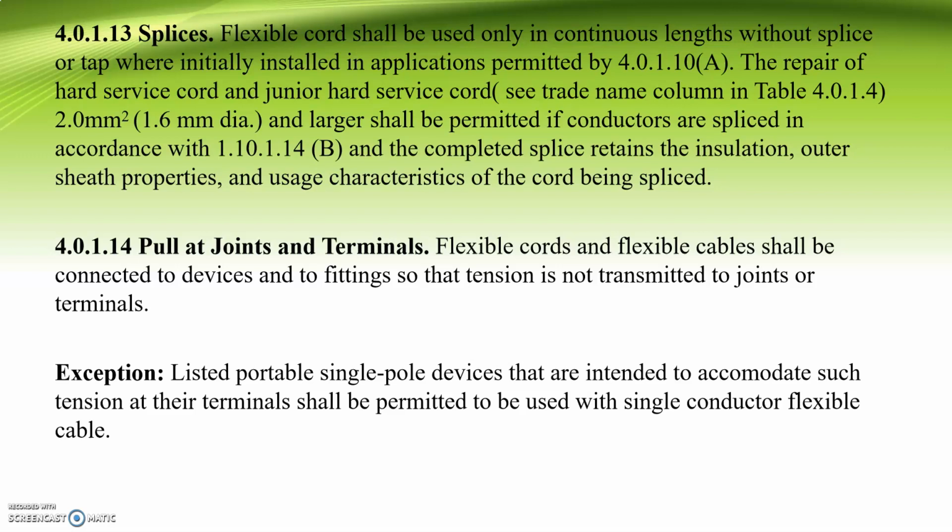Chapter 4.0.1.13, splices. Flexible cord shall be used only in continuous lengths without splice or tap where initially installed in applications permitted by Chapter 4.0.1.10a.